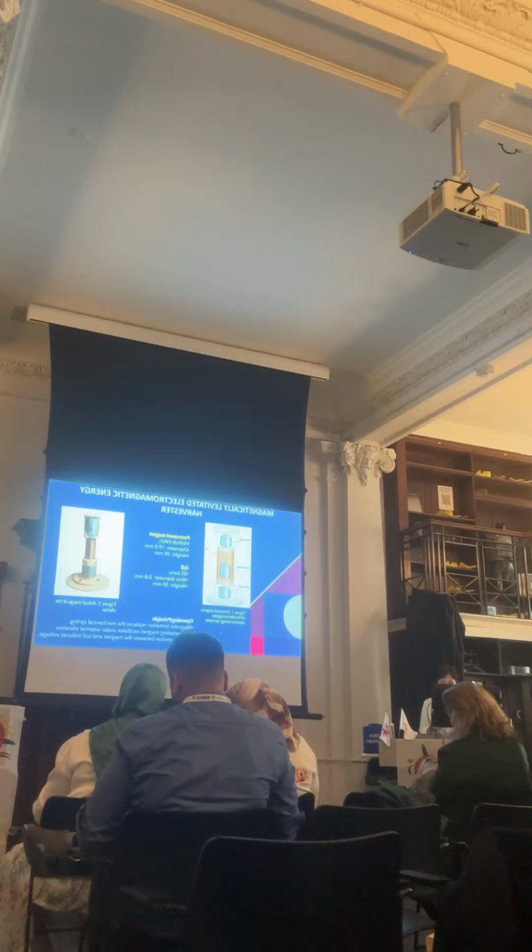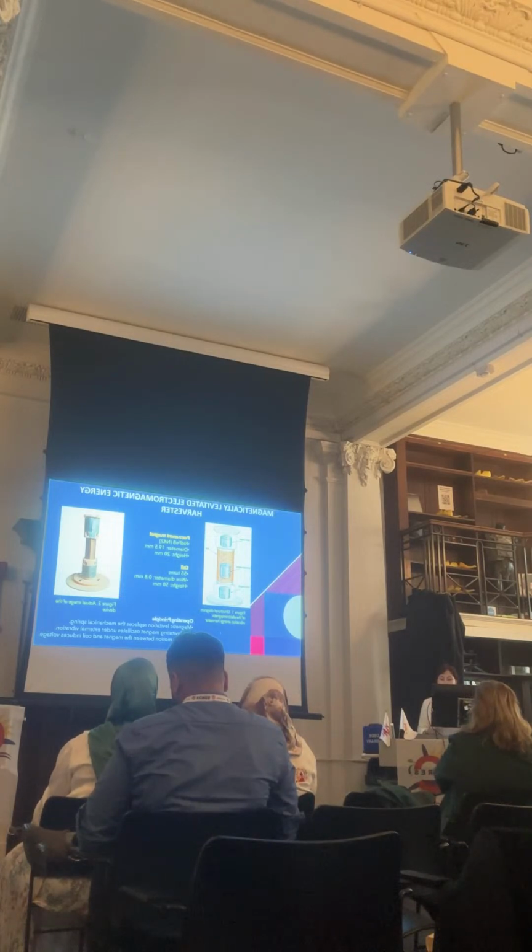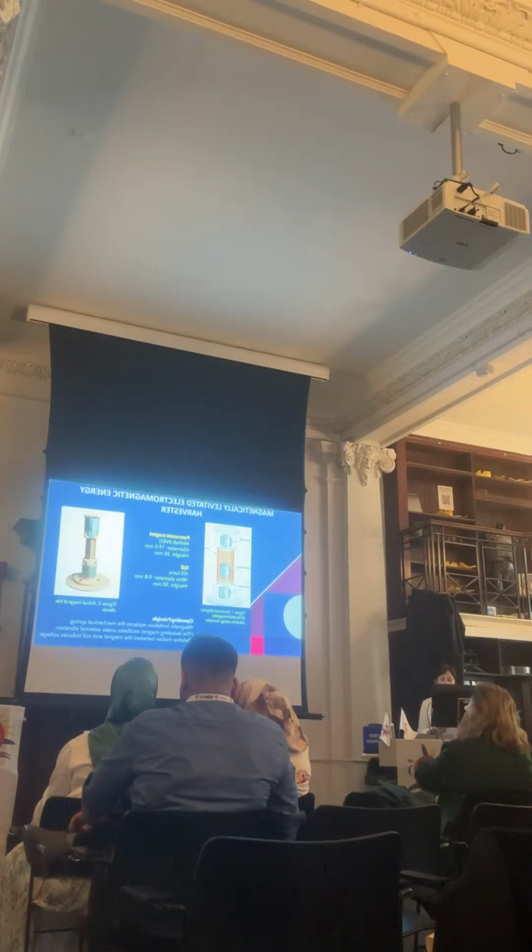When the device is subject to external vibration, the levitated magnet oscillates relative to the coil. The change in magnetic flux induces an electrical voltage in the coil. The non-linear magnetic restoring force makes this system an excellent platform for studying non-linear dynamic effects.